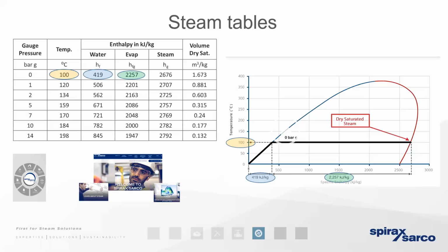And if we get an excess of condensate in the pipework, well, we're likely to encounter a starvation of steam at the process. So it's inevitable that there's going to be a delay in which the energy can pass into the process. The heat exchanger could be undersized. It means we've got to live with a longer and longer process time, more condensate in the pipework, and you'll remember we're likely to encounter more mechanical issues such as that erosion, the corrosion, and the water hammer.